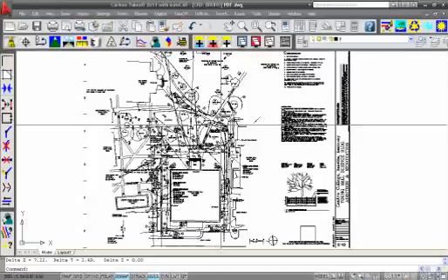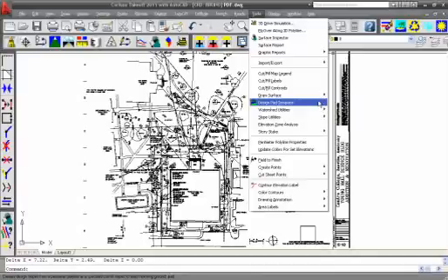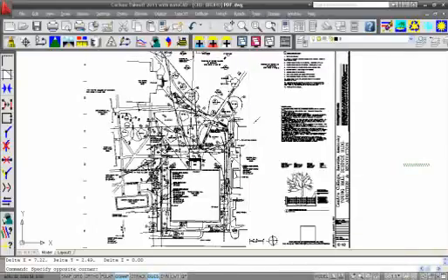And now we'd be ready to go through, create more layers for this PDF of the existing design, and then elevate the PDF. So those are some of the new tools that we've created for working with PDFs: the ability to recognize the layers and the different colors in the drawing and put those out to layers, the ability to process text and dash polylines into continuous lines, and to scale the PDF in a simpler fashion.